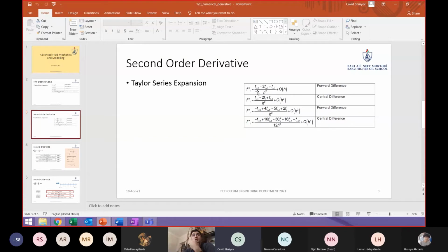And most importantly, our solution is going to be time dependent, which is the crucial part. We are going to use a for loop only for the times. Otherwise we are not going to use any for loop, because for loops in Python are very slow, and it's the same for MATLAB as well. At the initial stage, we may write for loops for filling the matrices, but then we are going to replicate the same scenarios with vector operations. Okay, we don't need for loops in order to fill the matrices.